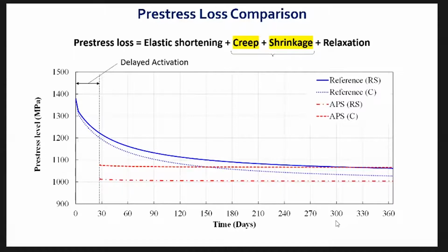And you can apply the pre-stress when it's needed, after a week or 2 or 3 even. By the time we apply the pre-stress, the concrete will have matured a little bit, and you see much less creep and shrinkage. And you see, long-term wise, they reach the same level of stress. So that's something that was very important.